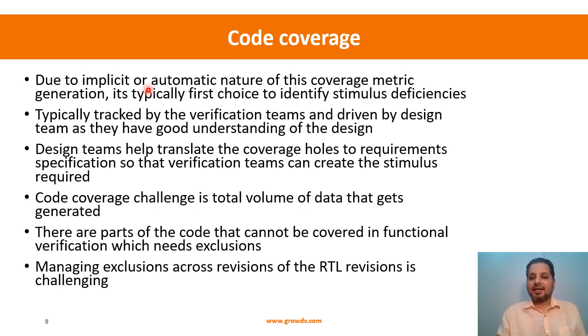And one of the challenges associated with code coverage management even till today is managing these exclusions. So you create these exclusions, let's say a particular expression has not been covered, and you say that particular expression is now excluded manually. But then there are revisions of RTL that keep happening, and that particular expression gets updated, or moves to a different line, and then again you need to go ahead and do this process of manually mapping it back and creating the exclusion.